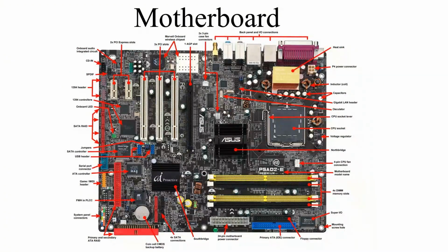When we do this, if power is not coming, the issue is with the SMPS. If power is coming, then the issue could be with the super IO controller, because when we put the power supply on, the super IO controller supplies or distributes the power to the motherboard. So that's the issue with this.